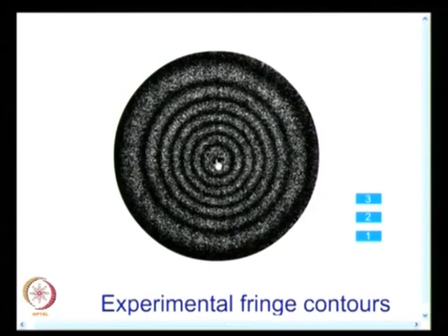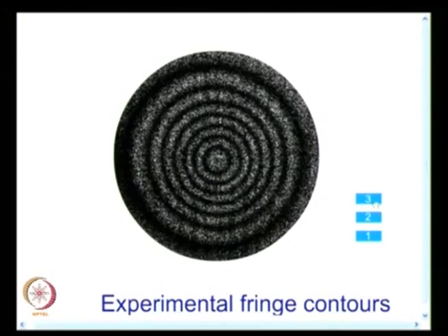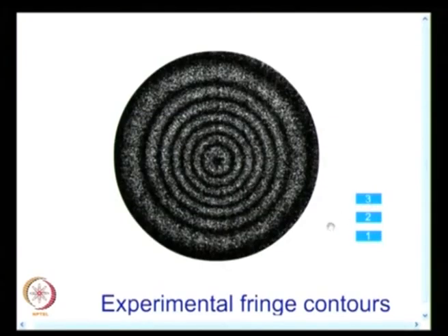What is the advantage here? You are able to get out of plane displacement by a whole field technique, but they do not have high contrast. So if you look at any of these speckle interferometric methods, they spend a lot of time on filtering. On the other hand, photoelastic fringes have very high contrast, and you need to do less post processing than in speckle interferometry. These are the fringes you have, again a function of load. Also make a neat, reasonable sketch of this.